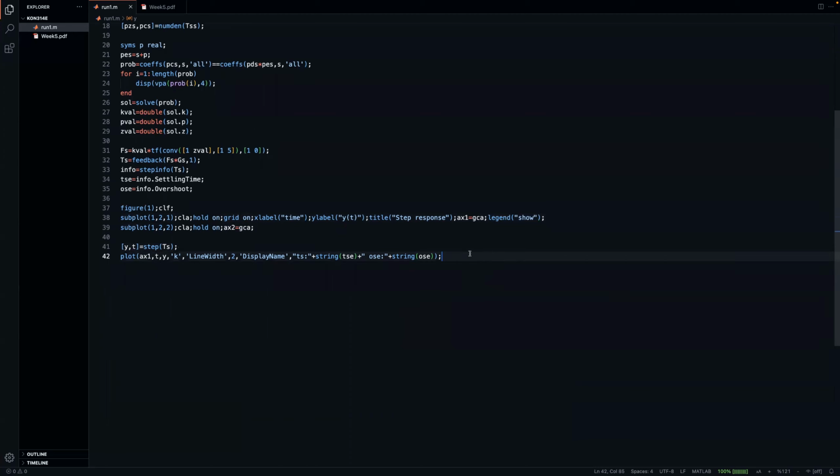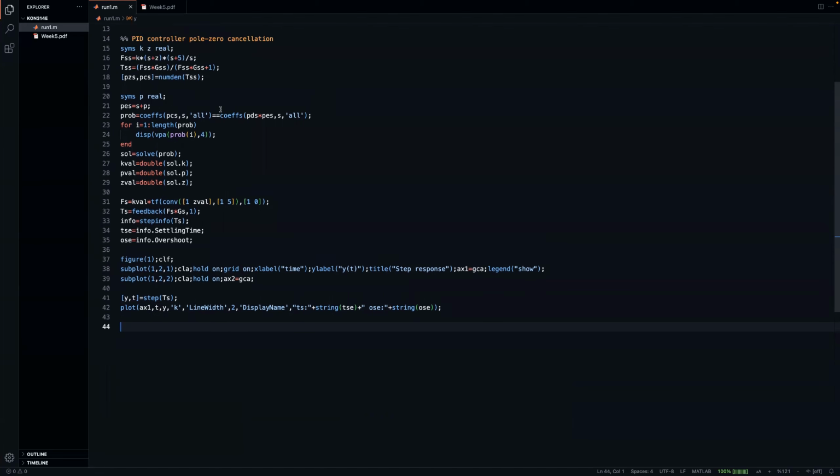There we go. Now, what I actually want to do is, since I know what I added to the system or the actual plant, I want to see the modified root locus. So the newly created dynamic parts added root locus. So therefore, I'm going to plot the root locus of GS. But what I need to do is I need to basically take the dynamic part of my controller. So if you're lazy, what you can do is you can just directly look at fs times gs. And when you're clicking on the root locus, you're looking for k equals 1.